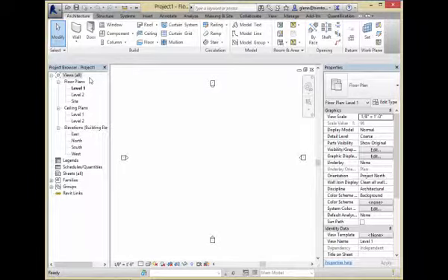But it's almost easier to have one floor that runs predominantly through the house and a slightly different variation there. And why it makes it a little bit easier, the problem some people are having is if you start breaking up the floor room by room, it's hard to get all the boundaries to line up perfectly. So when you start attaching walls, every once in a while it'll tell you, well, I can't join to that, there's nothing there. And usually what's happening is you hit a gap in your floor.